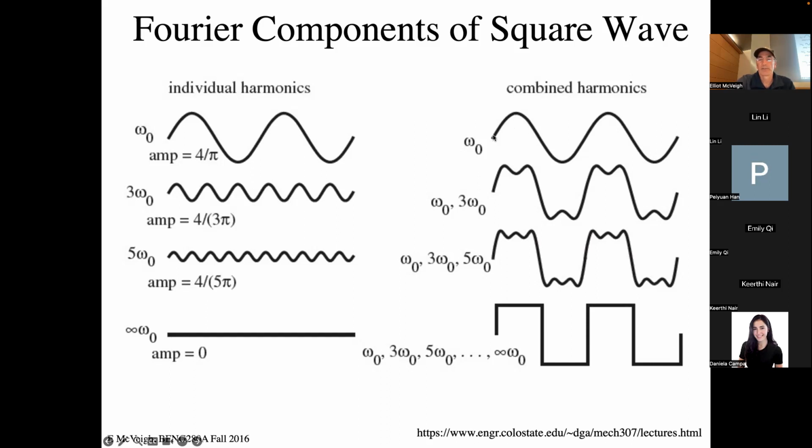So when we add up using those amplitudes, a sine wave and then a sine wave with 3 times the frequency, and then a sine wave with 5 times the frequency at this amplitude, this is what the sums look like until finally we do that many, many, many times and we get a square wave, right? Finally, we have frequencies that are almost infinitely high to produce these ridiculously sharp corners. But as we get to that higher and higher frequency, these coefficients get smaller and smaller and smaller, right?